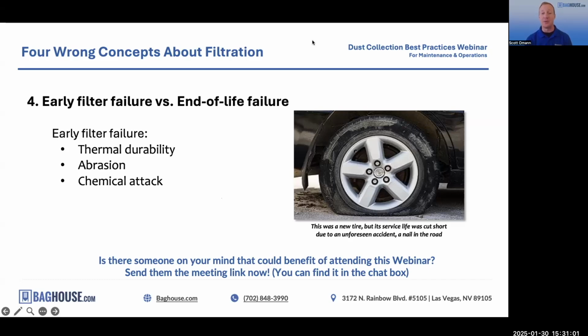Generally, our filters can only go about 15 or 20 minutes with that excess high temperature rating. Maybe we sucked up a spark or some sort of ember that physically caught the bags on fire, or maybe they just damaged them. So it'd be the first reason as to why our bags would fail, some sort of thermal abrasion, or something that happened via temperature.